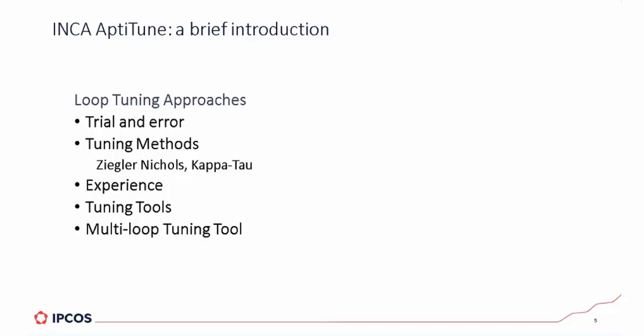And based on the speed of the response, he can give you an indication of what the integral time should look like already. So based on experience, you can come to a tuning upfront already, given these pieces of information that I mentioned.